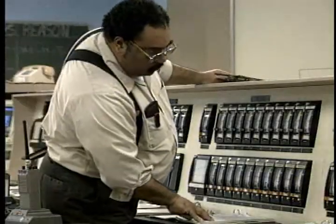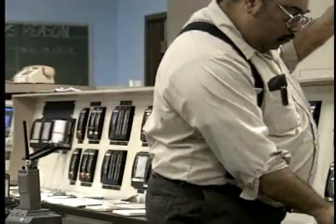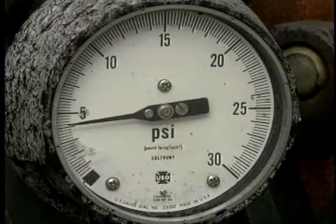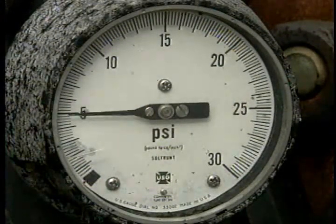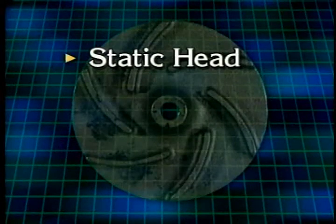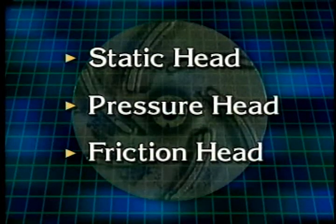Careful monitoring often allows you to know in advance when a pump needs to be pulled out of service for replacement or overhauling. Let's start with pressure, or head as it is called, in a centrifugal pump. Think of head as the work a pump must do in order to move fluid through a system. The total head in a system has three parts: static head, pressure head, and friction head. Each of these is just a different kind of work that the pump must do. We'll discuss each of these in turn, and we'll show you how they are calculated.